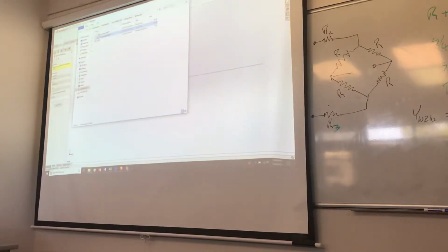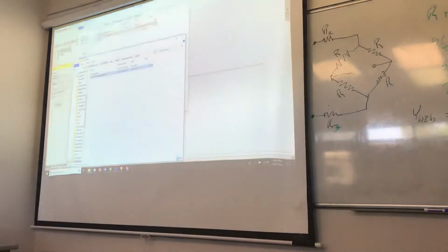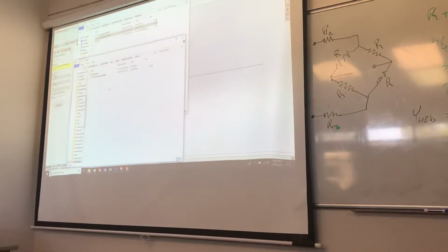We get to go back to our weldments thing here again. Where we have our weldment profile and our custom, and you're going to have to build another directory in here, make another folder under the custom one that is, in my case, rectangles, and I'm going to move that one into there. It's going to ask me if I want to do that.